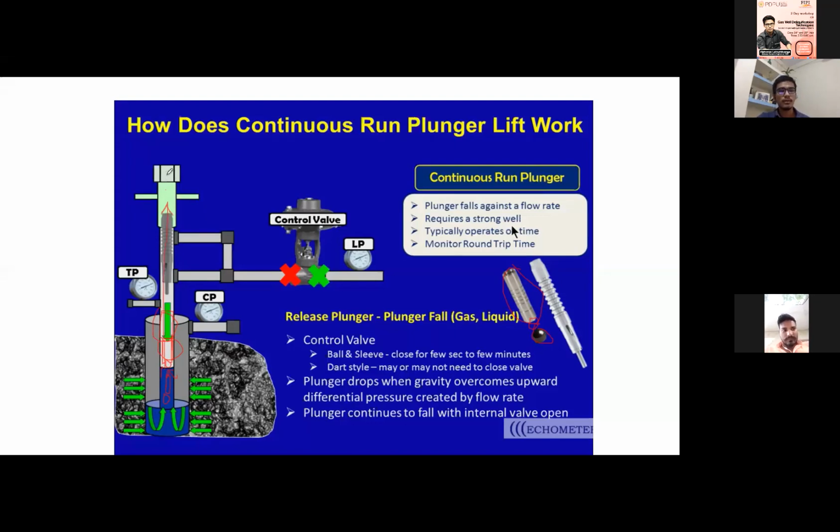And in the lubricator at the surface, you have one stick. When the plunger goes to the surface, this plunger with the ball will hit the stick, and this ball will drop back inside the well, above the bumper spring.